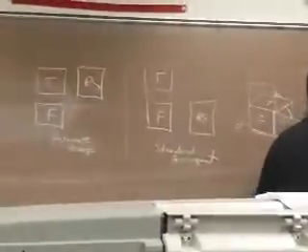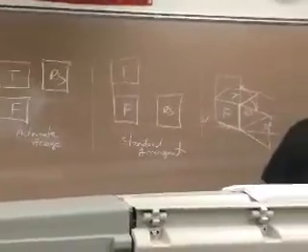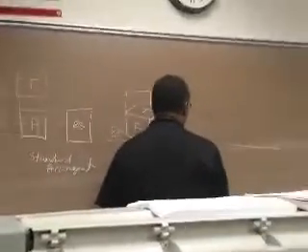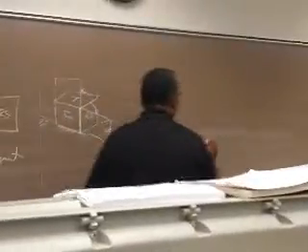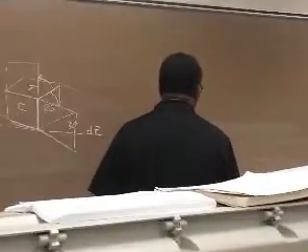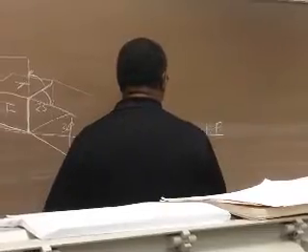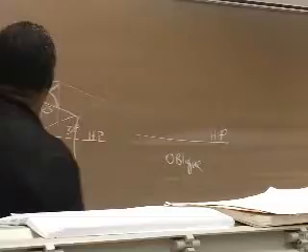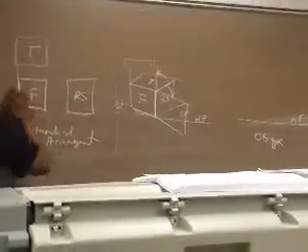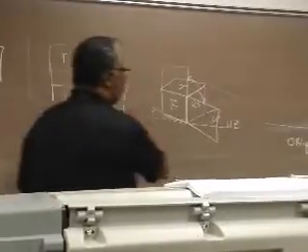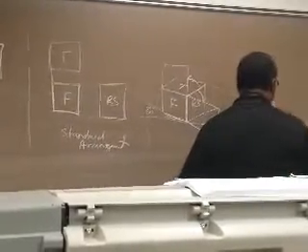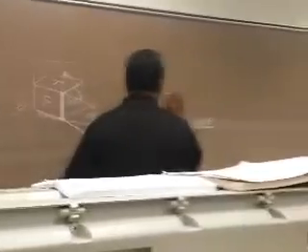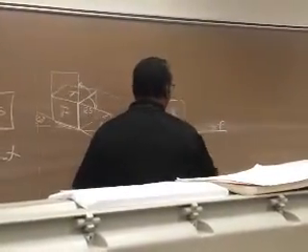Now when we're dealing with an oblique drawing, if this is our horizontal plane here, the object is not rotated. You take the view, whichever view you use, you take the view as it is, and it's placed like so.